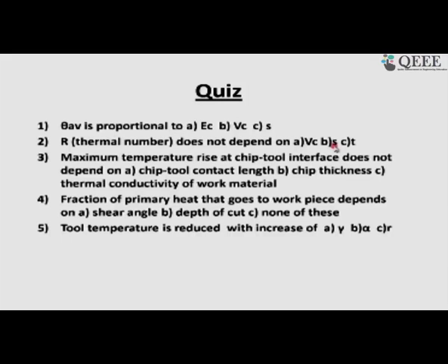And maximum temperature rise at chip tool interface does not depend on chip tool contact length or chip thickness or thermal conductivity of the work material. It does not depend on chip tool contact length or chip thickness, but it does depend on thermal conductivity of the material, at the chip tool interface.